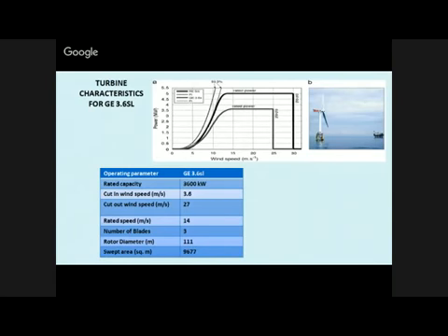So that is 27, which is quite high. Particularly, only in the stormy season does the velocity increase more than that. Otherwise, wind velocity will always be lower than that. Then the rated speed is 14 meters per second, where when that speed is achieved, the turbine will work at its own rated capacity, with maximum power. The rated capacity is 3.6, so at 14 meters per second, it can generate 3.5 megawatt. Megawatt multiplied by hours.